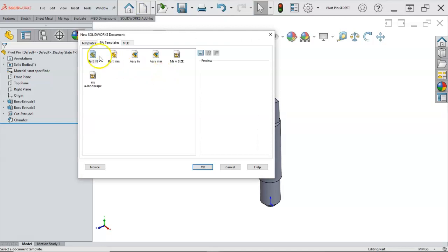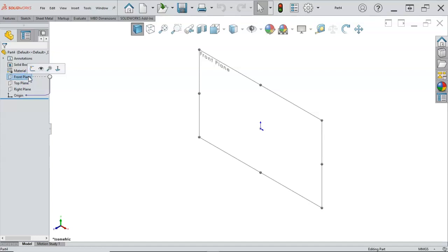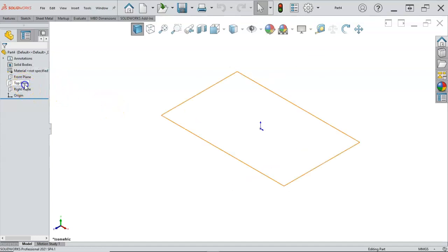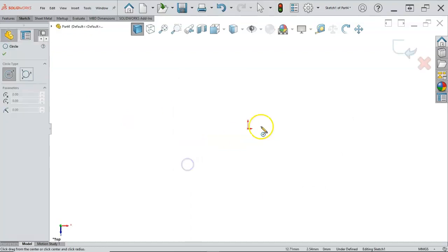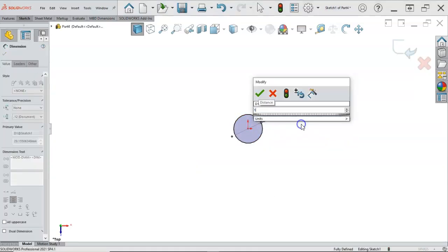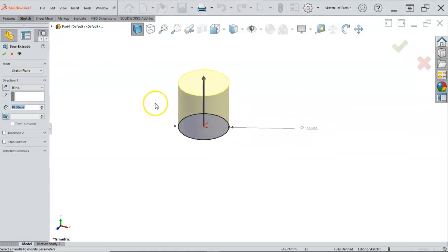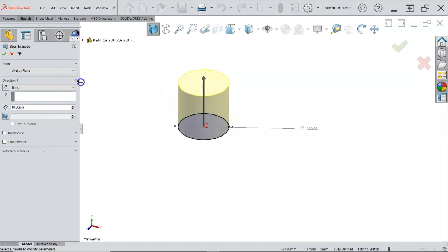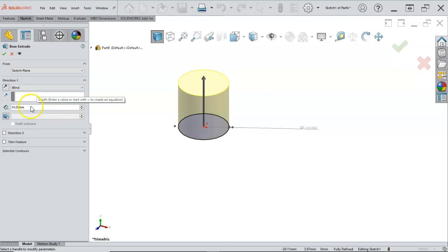One more, new part millimeter. And if we did that, I don't think we need to do that one as a revolve. This one probably will work out a little bit better with the S key, the circle. We'll put our 10 millimeters in. Features, extrude. You might notice that I have a habit when I'm not thinking about the right mouse button or the S key of going up to the features, and that's fine. Whatever you're most comfortable with. And that's pretty much what I default to.